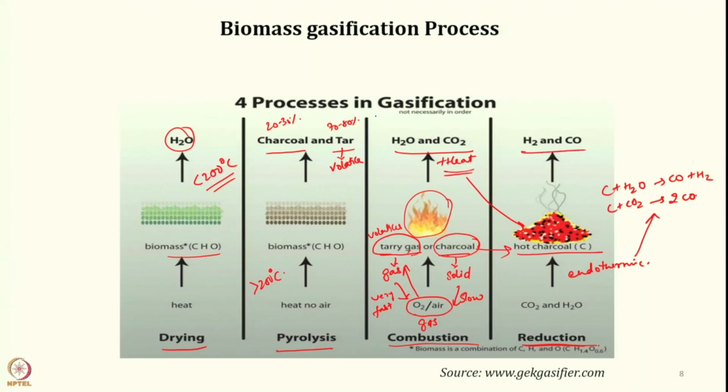What are the four steps of gasification? The first is the drying process. Suppose you have wet wood chips. Firstly you have to dry them, below 200 degrees centigrade.